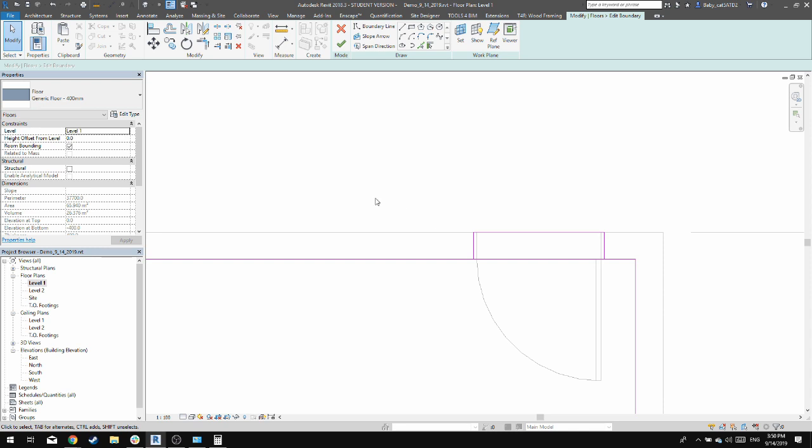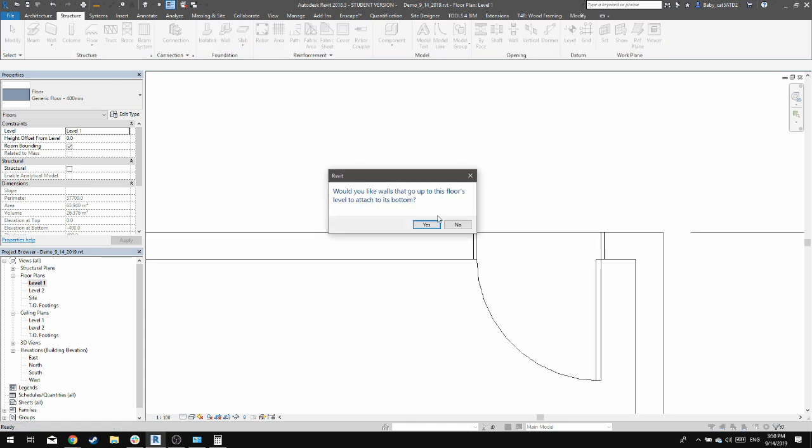And now we're going to use a new tool called the Trim or Extend tool. This one is amazing. The shortcut for it is TR. And you're going to click on one line, the end of the line that you don't want cut. And you're going to select the next line, and it'll trim the line so that any of the excess material is deleted. And this is going to save you a bunch of time when you have to do a bunch of things. So you just click check mark again to finish this.